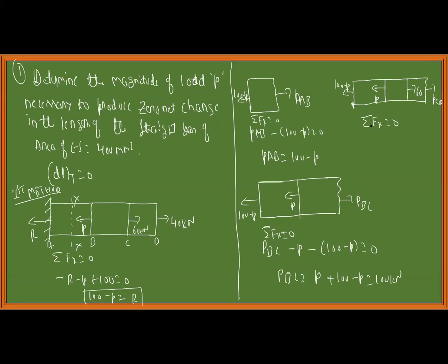For example, stress is a tensor. I cannot indicate the difference between pressure and stress. Pressure is force per unit area. It has the same unit as stress, but stress is a tensor. If I write sigma xx, it means the normal to the plane is in x direction and the stress is acting in the x direction.